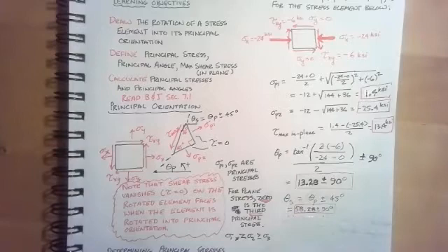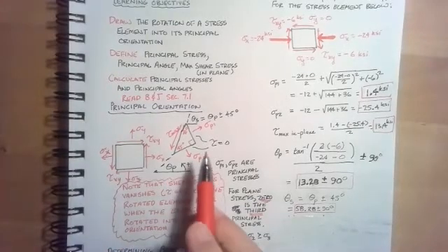But we knew that the components of whatever force, whatever traction was acting on a particular plane would have to be resolved into normal and shear components, and we would also have a change in area that had to be accounted for. So the stresses on an oblique plane were dependent on the angle of rotation of the oblique plane with respect to the cross section. And something similar is happening here.